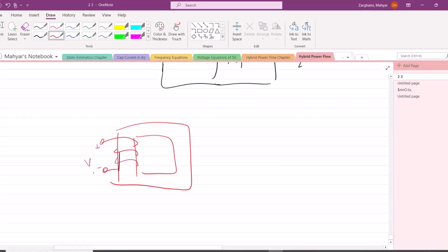The same way that the voltage is induced in this winding, because most of my magnetic materials are conductors of electricity themselves, we would have certain areas, certain loops here where voltage is induced. And because I have conducting material inside my magnetic material, it would cause some losses. This loss is different from hysteresis losses.